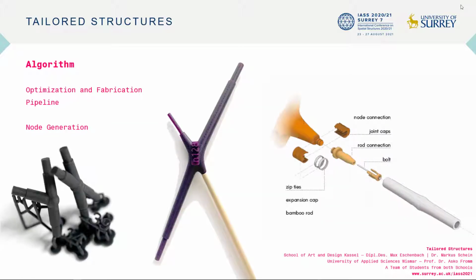To connect the final members, we designed three different joint types so far: a quick and primitive version on the left-hand side, a more sophisticated one using Daniel Piker's Multipipe component. We can nicely see how this joint can adapt to different lengths and diameter situations. And finally, there is the bamboo version, where the Multipipe version is enhanced by a rationalized serial expansion friction mechanism.